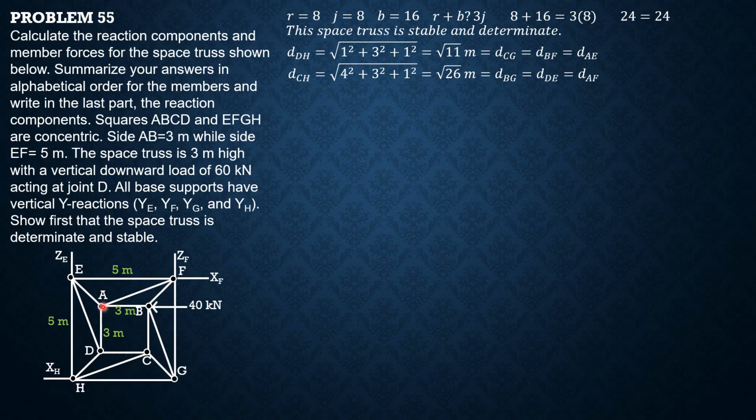So again, the stress in AD is 0 at A by a special rule: when all forces lie on a single plane, the one that is not lying on that plane is 0. Then if we proceed to joint C, again we have CD, CH, and CG lying on a single plane, and BC not on the plane, therefore stress in BC is 0 at C.